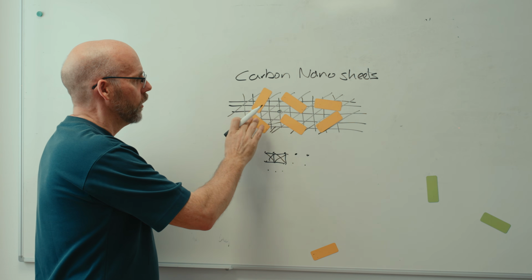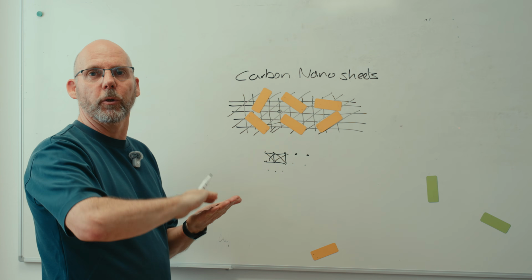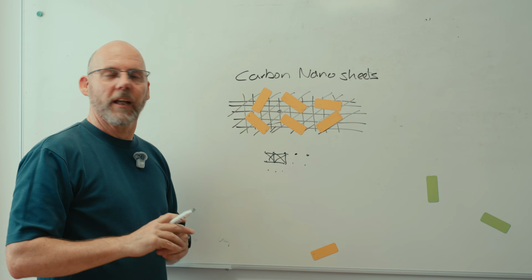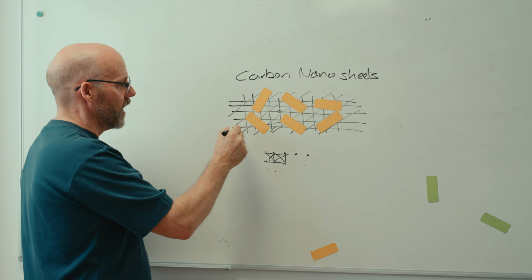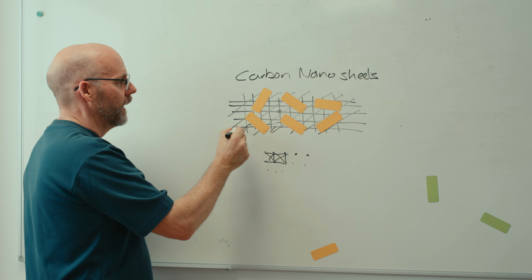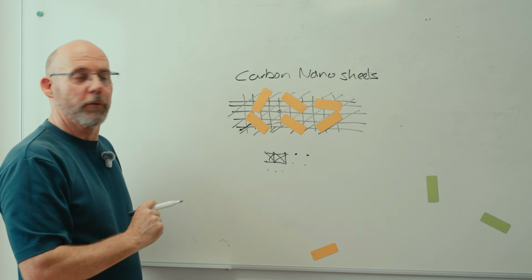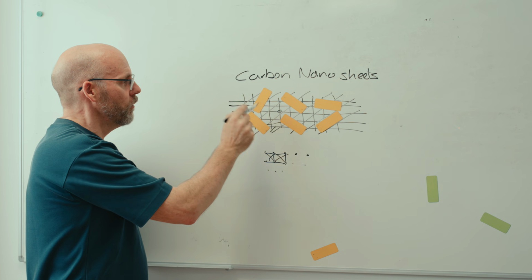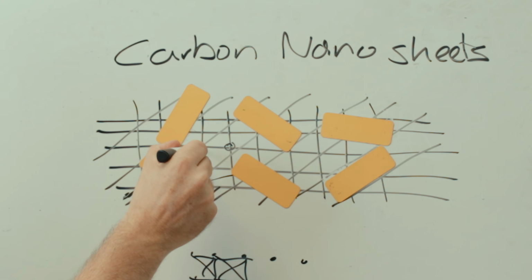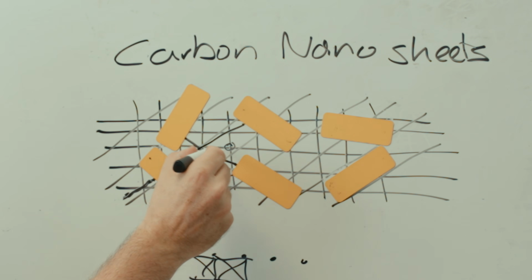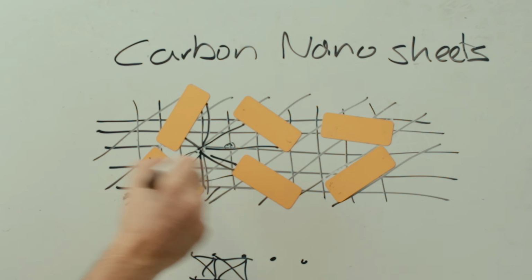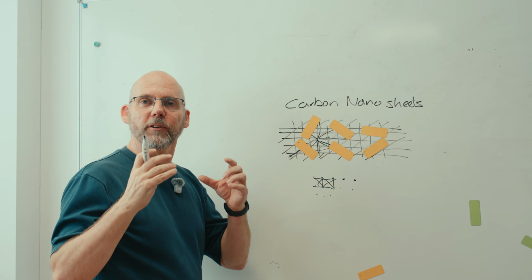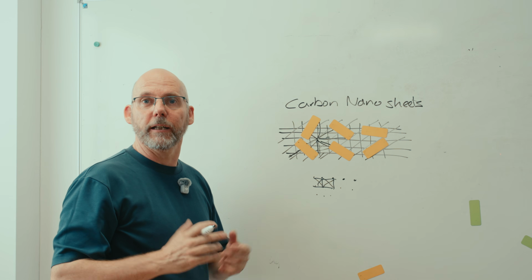And we will be putting those in the outer layer, either the coating or the outer layer of epoxy on the carbon fiber. And what will happen? Normally, if you have a tear, let's say we start tearing from here, it will tear through. It will get to this nanofiber sheet and it will stop. It will stop on the edge here. So if you put enough of those close by, if you have an impact here, it will start radiating out, but it will stop once it hits the nanosheet. So if you do enough of those, it will get so strong that it will actually resist shearing, tearing, and coming apart.